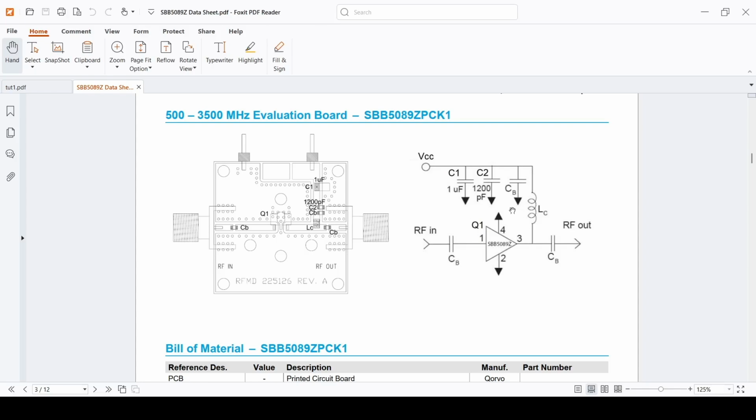Another filtering effect, and also another way to stabilize the supply, is by having some capacitors, which can provide the current when the rate of change of the current is high. Usually when we add more capacitors, it helps us because it reduces the noise, and it also acts as a reservoir for charge in case we need it, right?